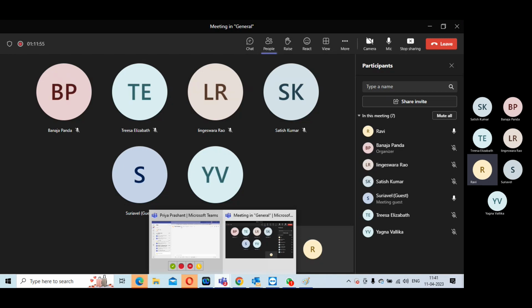In addition to that, the first thing you are addressing, even before you touch the stuff, is the data flow. So your data flow and your floor plan should be the focus. Data flow says, I am supposed to get the input over here and there, but if you have done entirely the opposite thing, then it's a different ball game. So you have to take care of your front-end architecture, what the requirement of the block is, and place accordingly, and in that the first thing you should address is congestion. Cover the data flow because that's your key part, how your whole stuff is going to work.